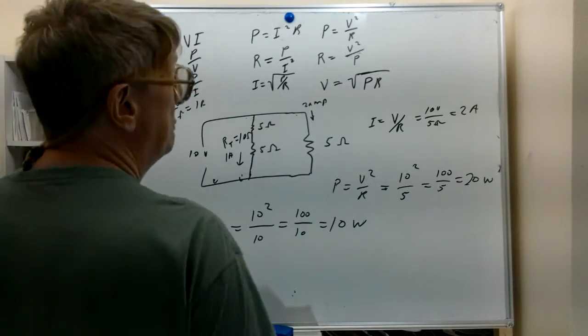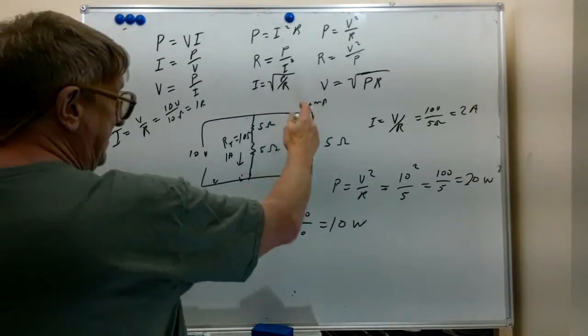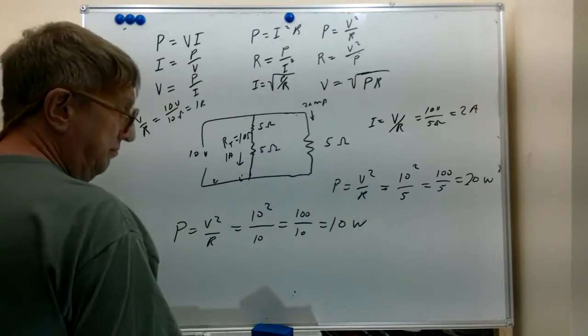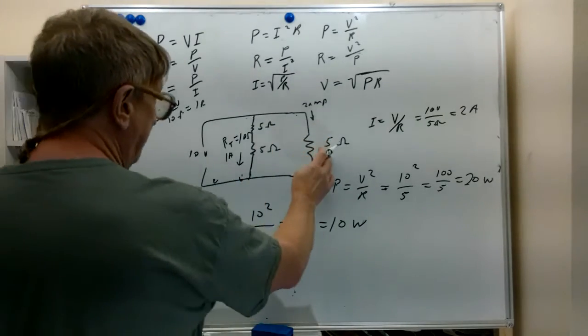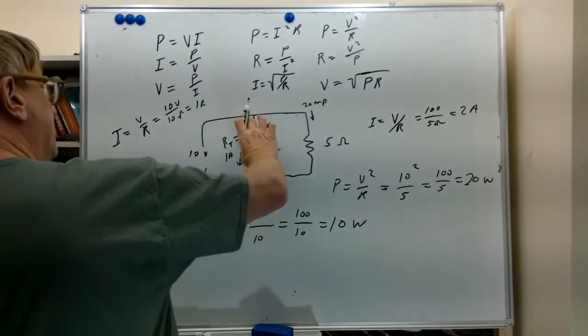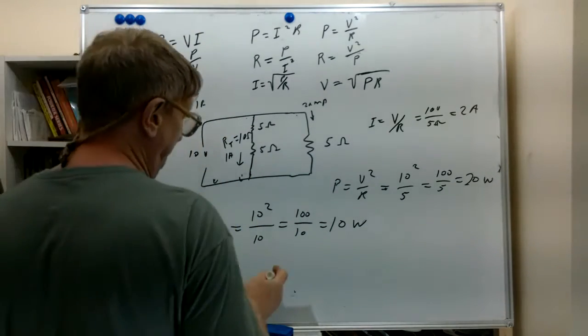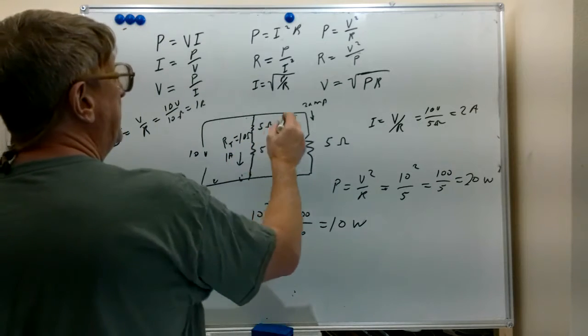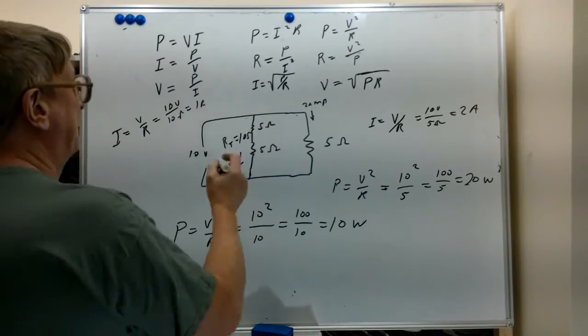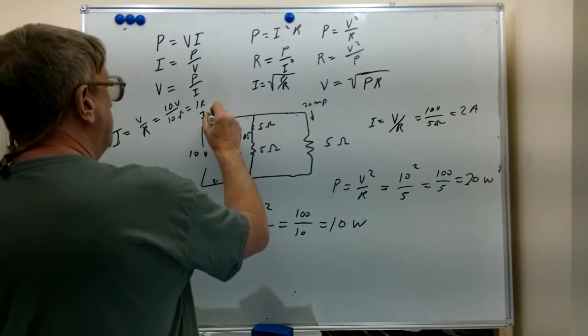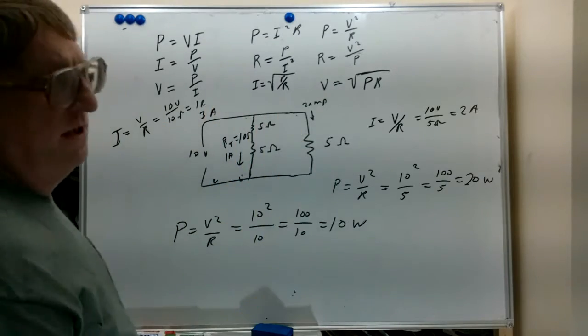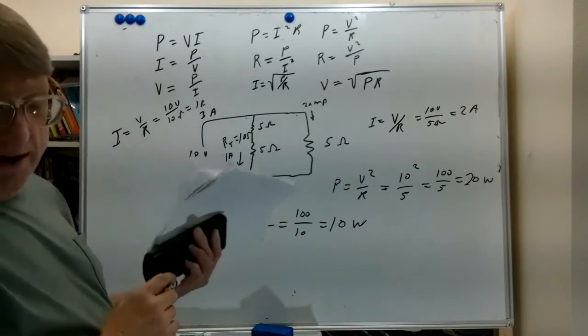And we hook it back up, we have 20 watts being dissipated in this branch of the circuit as heat in that resistor, and the 10 watts over here is heat in those 2 resistors. We have 1 amp here, 2 amps here. Our power supply is going to have to supply a total of 3 amps because it's got to supply enough current for both of the branches.